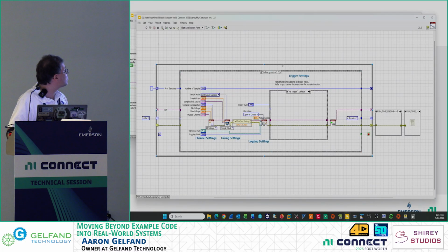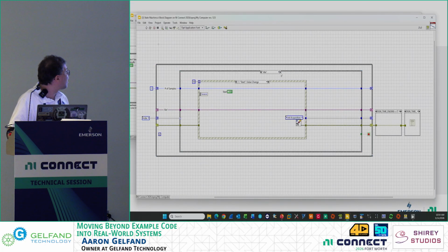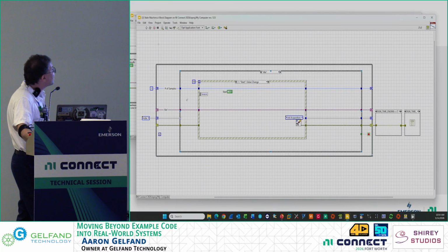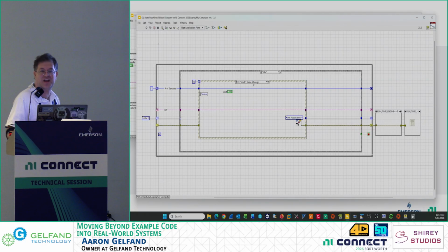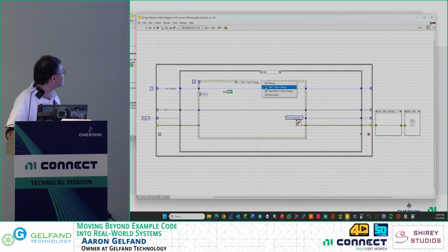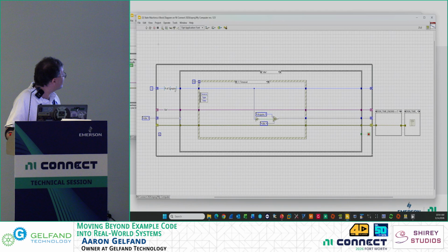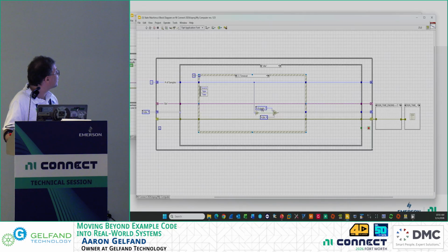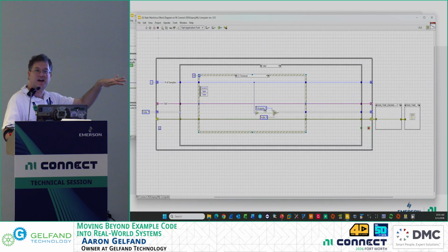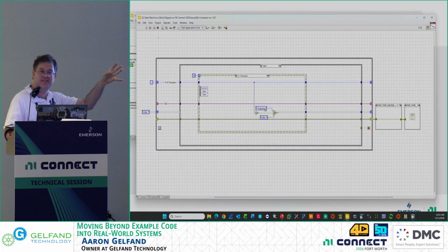So when we go back to our idle state, it has a timeout, and I've got it as 10 milliseconds, so pretty responsive while still saying I'm not going to overload my CPU on idle. In the timeout, if the number of samples isn't equal to -1, because we've told it to start acquiring, I go to the acquire state, acquire my data, come back to idle, and check to make sure the user hasn't pressed the button.